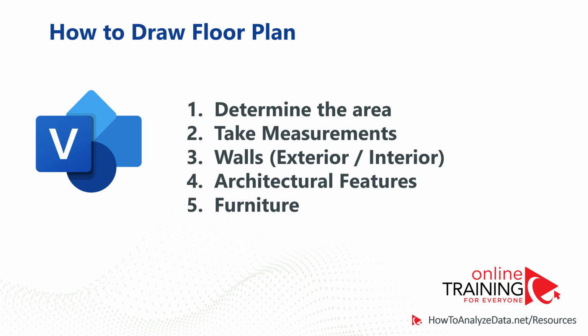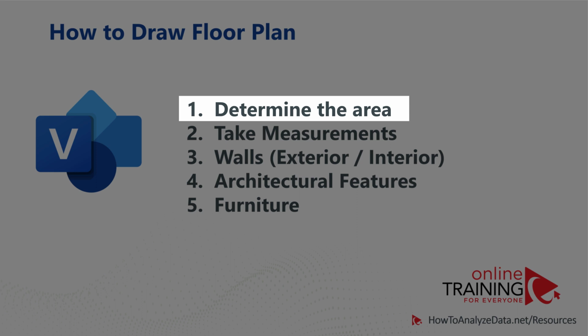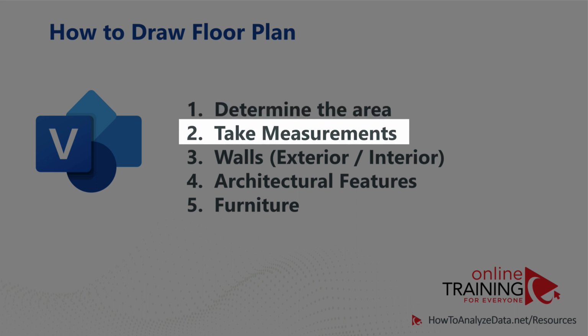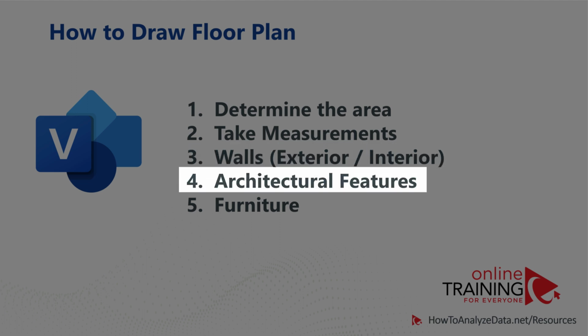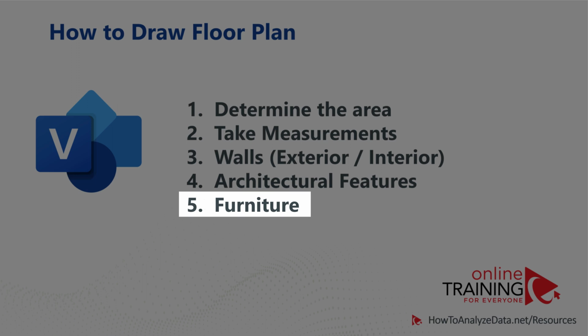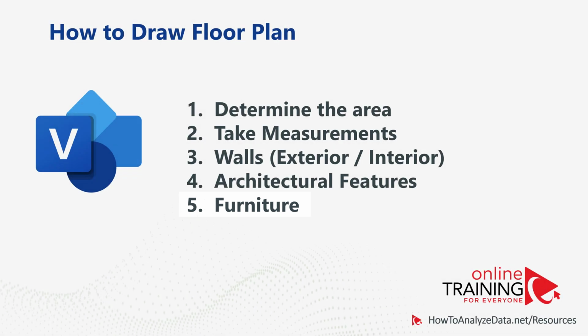Designing and drawing floor plan in Microsoft Visio is very easy, but you need to keep in mind a couple important considerations. You need to determine the area that you're trying to draw. You need to take measurements if this is an existing area. You need to first focus on the walls, interior and exterior, and separate them in your drawings. You also need to keep in mind architectural features for the diagram, as well as the furniture and fixtures that you would need to place into your drawing.